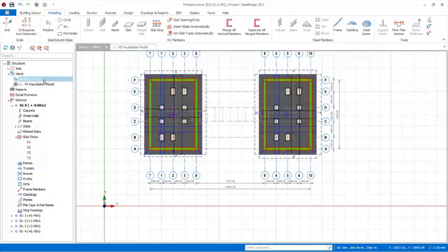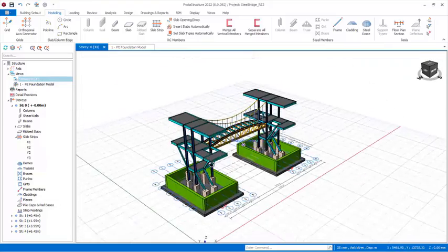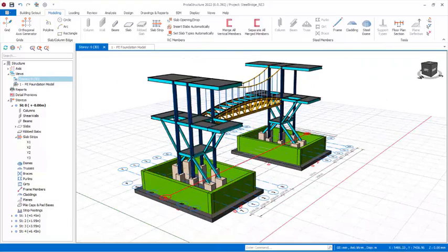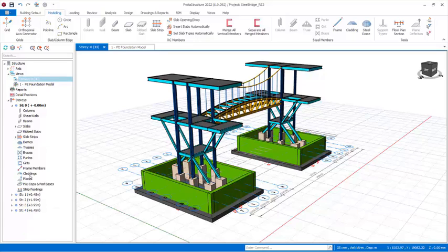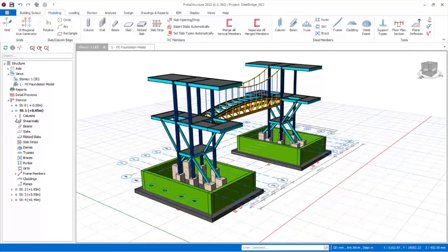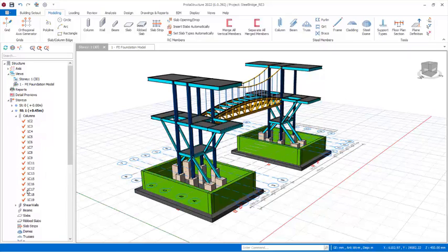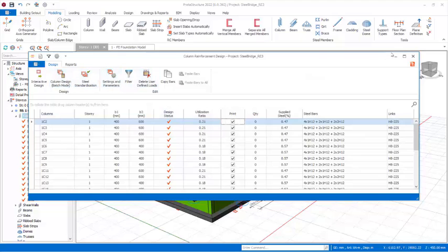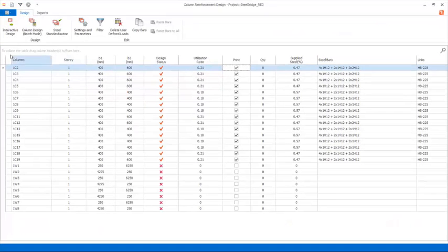You can now navigate to the 3D and see what you've done so far. So you have something of this kind. How about the reinforced concrete columns? We can't go into designing that right away. We need to navigate to Story 1, expand this. You can see it is showing a nullified analysis sign, having this gray sign right there. So you have to use these options over to this dialog where you can carry out the interactive design using the batch mode.